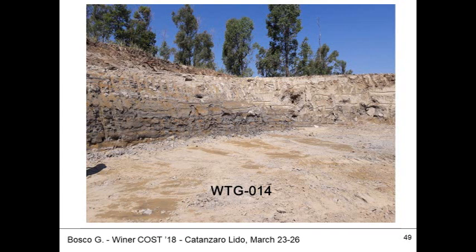below a superficial layer. The information we have in terms of water circulation are nil, because the variety of the soils does not make it simpler, and because we don't have a network of piezometers, and not only standpipes, but essentially 4 water pressure measurement piezometers to understand what is going on.